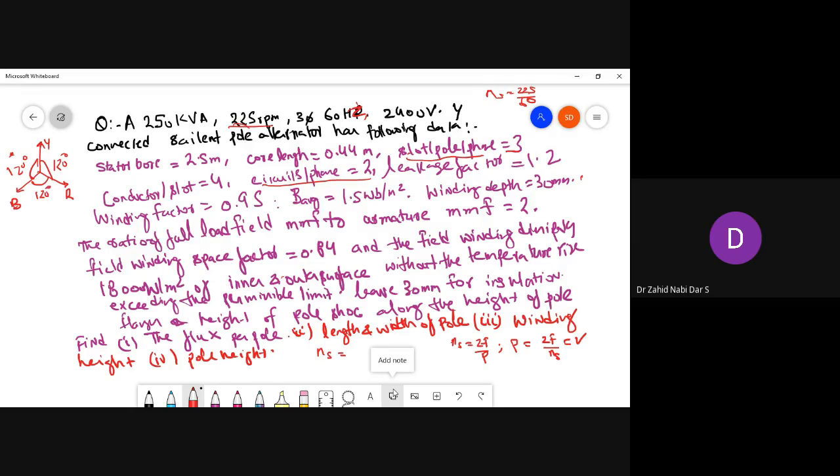Now circuits in a single phase: suppose I have this circuit, phase and neutral. This is a single phase system. Now, if I want to create two circuits per phase, I can create two circuits. Let this be the neutral part. From here to here I have 230 volts. From here to here I have 115 volts.